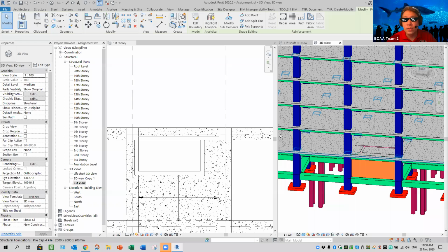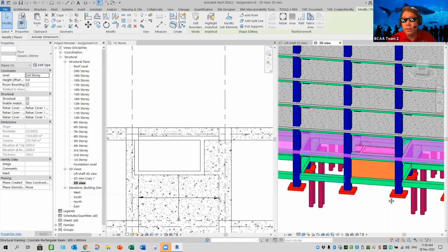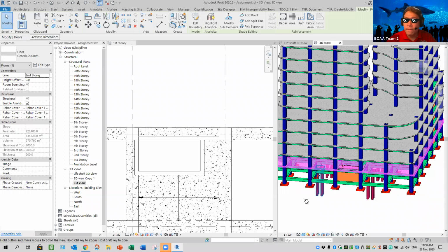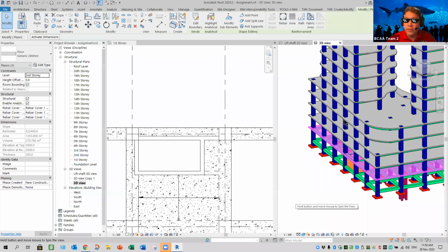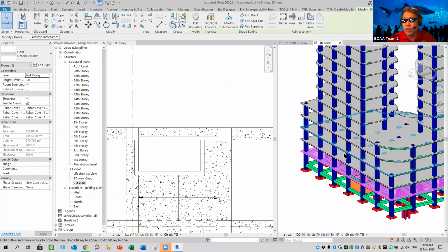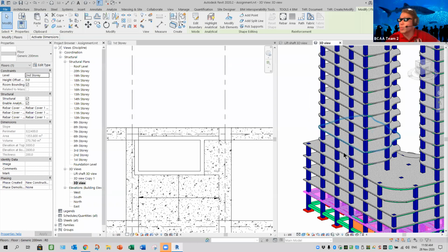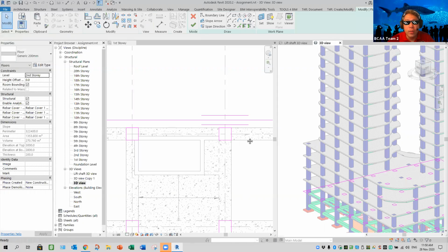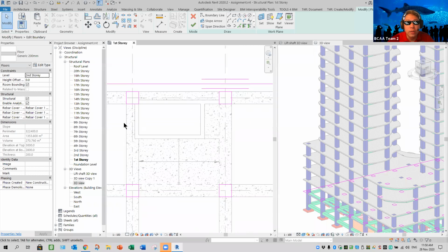No choice. Okay, see the slab. You could have modified this view, then the rest here, if it's identical, you modify one, then simply duplicate up. Yeah. Okay, so for this, I just simply edit boundary. What I want to cut for this is one big hole here.